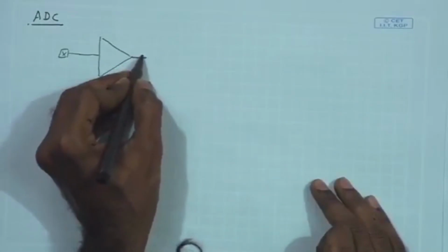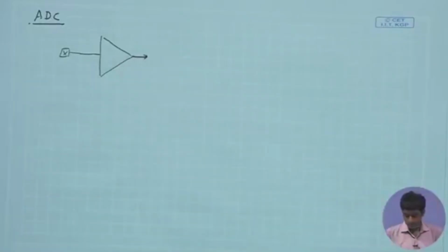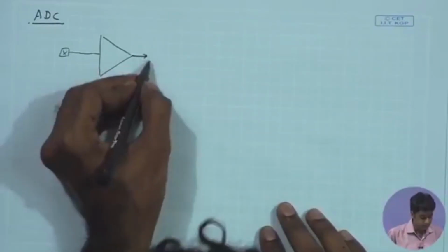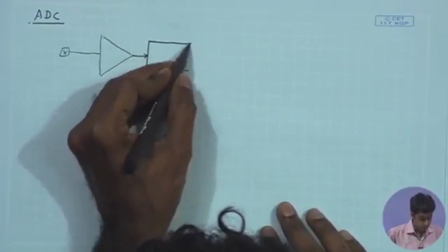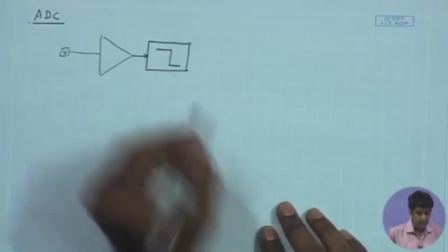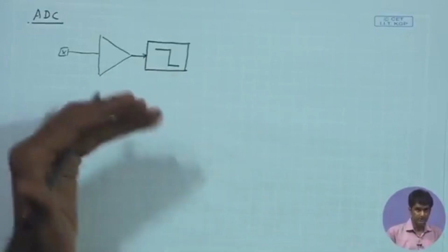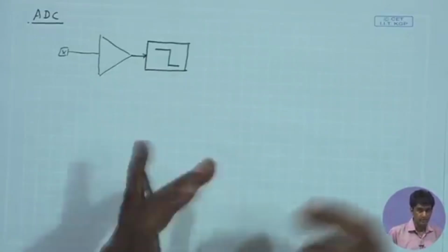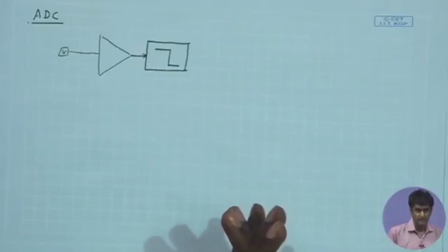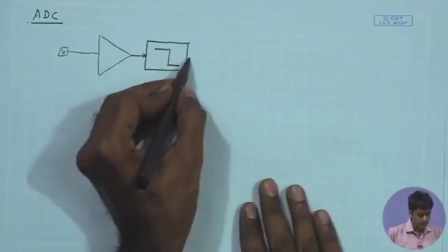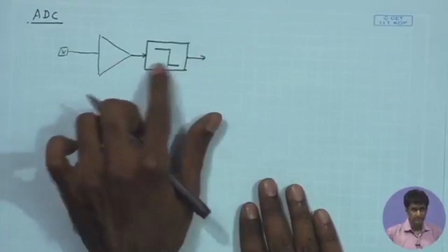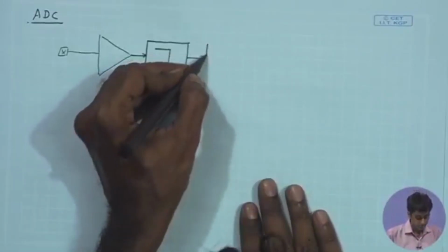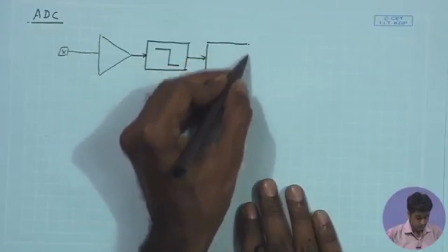Likewise, we have discussion on the low pass filter, the anti-aliasing filter, which is supposed to reject high frequency noise, and there we saw that we can use some special techniques like GMC filter for implementing very low frequency cutoffs. And finally, we have the processed amplified filtered signal, which is going to the A to D converter over here.